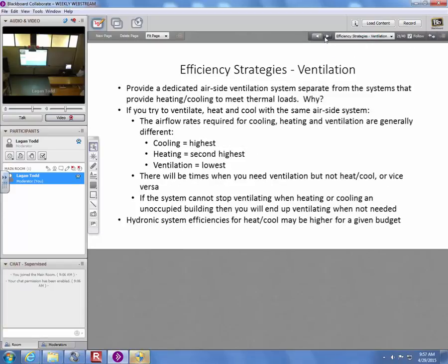So let's see. Is that becoming more standard also, to keep those two systems separate? You know, it's hard to say in the residential world. I mean, when we started saying in residential building, okay, we need ventilation that's somewhat active, controlled, the first step was, okay, let's just put in more bathroom and kitchen fans, maybe tie them together into a central fan, whatever. Okay, that's decoupled. Your ventilation there has nothing to do with your heating and cooling. I mean, they interact. So when I say decoupled, I mean from a design sense. They certainly do interact with one another because of how much ventilation you bring in.